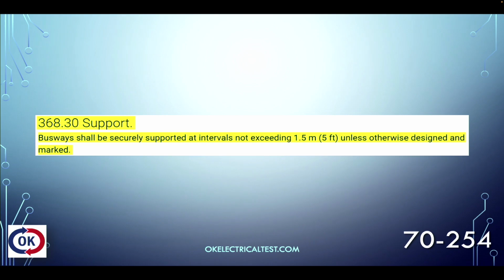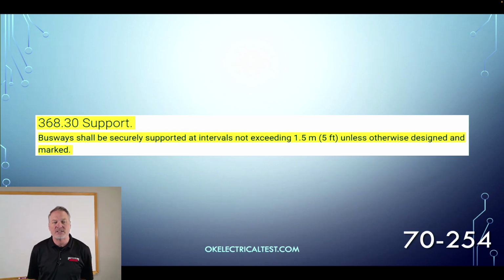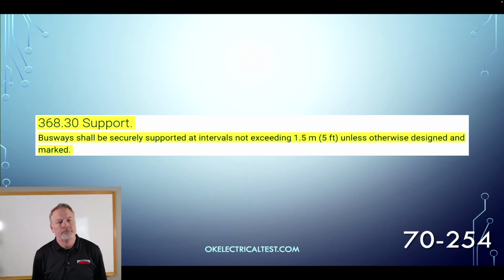Still under busways, we've got 368.30 support, so this is going to be our support of our busways. It says, busways shall be securely supported in intervals not exceeding 5 feet unless otherwise designed and marked. So every 5 feet we need to support our busways.